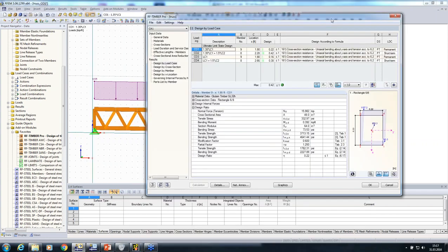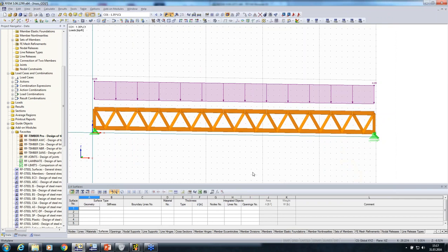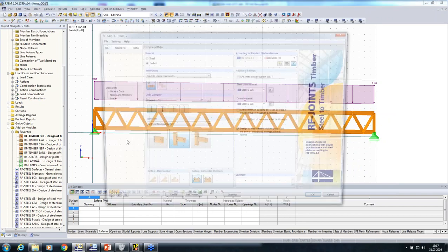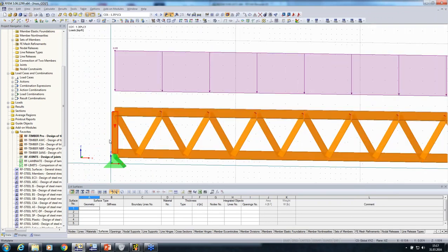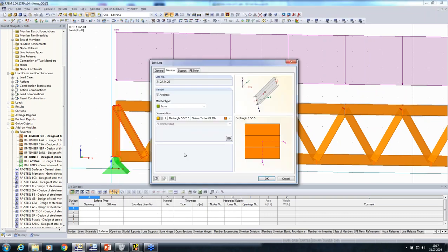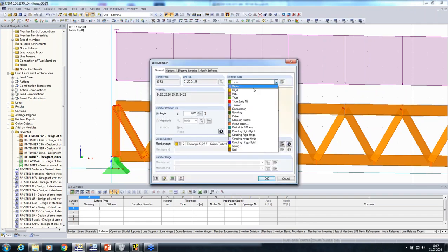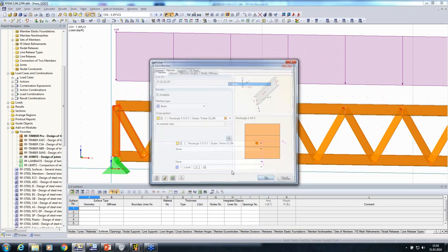That's pretty low, but we must also consider the connections in between, which will narrow the profile one more time. And so to have a loading of 60–70% is pretty common for this kind of trusses. And now I would go to joints, but I forgot one thing. Joints is able to create stiffnesses itself, and therefore I need to change the truss beams one more time, from truss to beam, and make a moment hinge on the end.